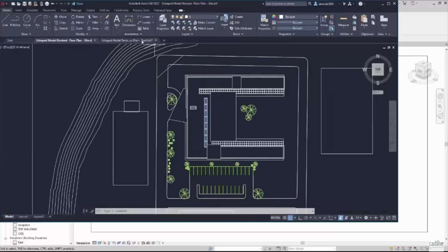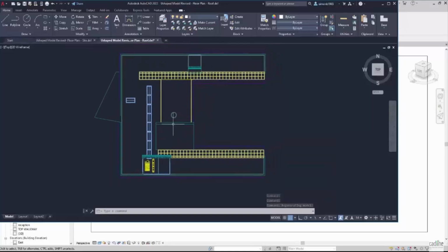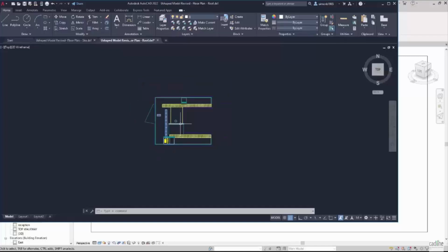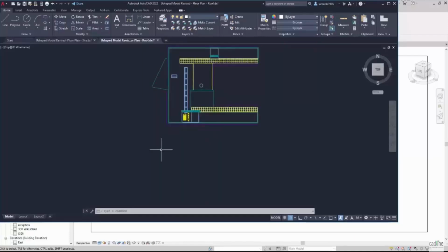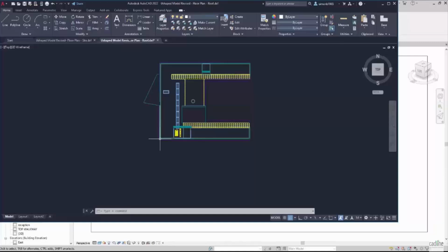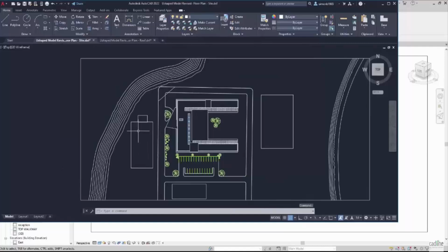If for example you have the roof space of the layout, what you would effectively do is take a copy of perhaps your roof space drawing. You would then zoom out and then you would XREF the surrounding site plan so the origin is in the same place. So you'd basically need to move the origin of the site plan to relate to your building that you're doing the analysis on. So let's say the outside corner of this building here. XREF the site plan in. You then get your site plan with your target buildings that you're going to model using the same origin. And you would then save that as a DXF file and use that as the basis of the site plan in the MEP Works program.